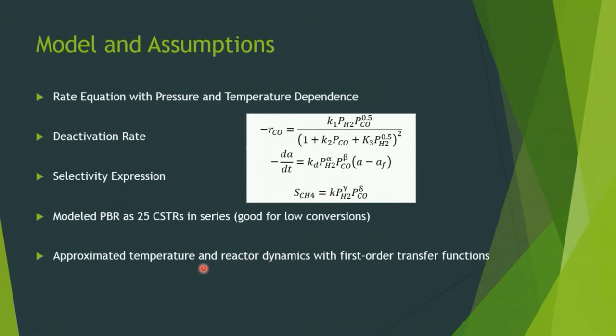From also experience in Dr. Hecker's lab, we used a transfer function with a time constant of 1 hour to approximate the transfer function of temperature changes, as well as a 5-hour time constant for approximating the reactor dynamics.